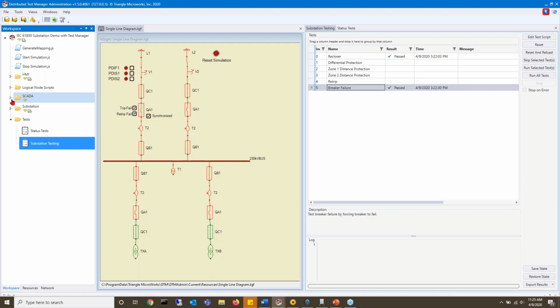As for scripting, yes, you can set up all sorts of events regardless of protocol. But later in the presentation, I'll show you different ways that you can set up the initial conditions, including scripting, but there are also a few other ways you could do that as well. Specifically, I'm thinking like a CSV file where you go through and you set up the initial conditions for all your different devices at once, and you could step through different states.